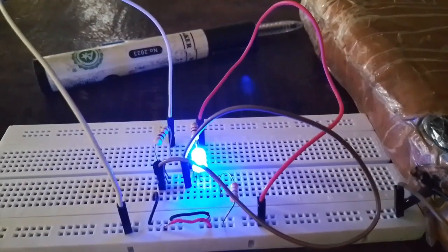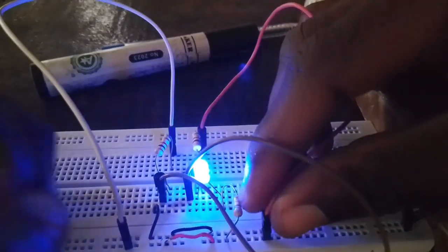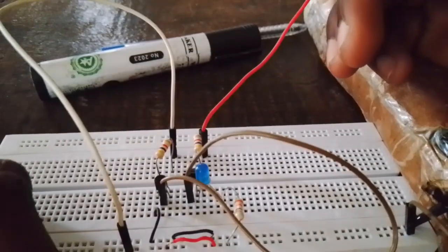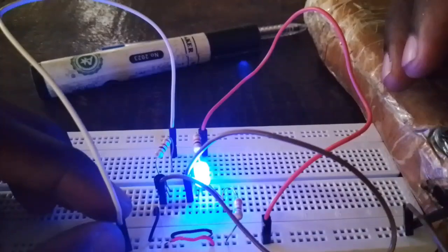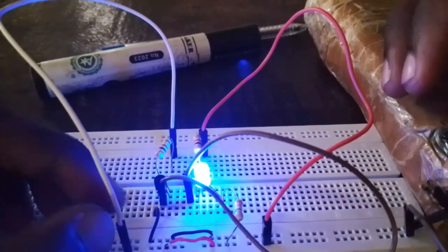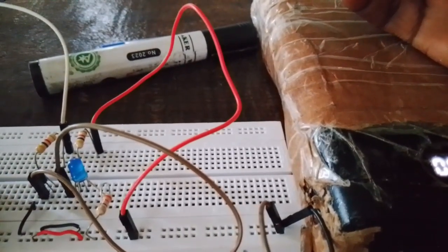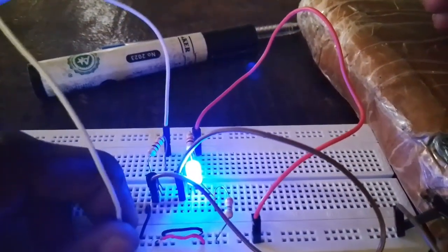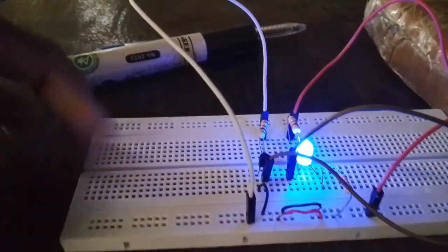So can you see that for an AND gate, until the two inputs are 1, our output cannot be 1. If our input A was 1 and input B was 0, the output is going to be 0. And if our input A was 0 and input B was 1, the output is also 0. So for you to have an output of 1 in your AND gate, your two inputs must be 1. So that is it about the AND gate.